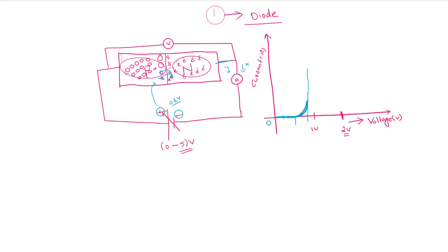Now when the voltage starts at 0.7 volts, it started conducting and going on, and whenever it is further increasing, maybe 0.8, 0.9, even less than 1 volt, the current keeps increasing. So these characteristics are called forward bias diode characteristics.